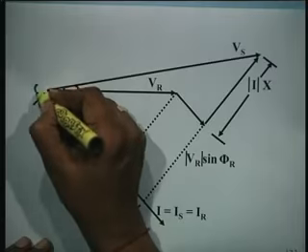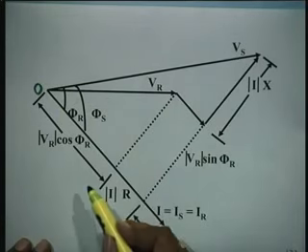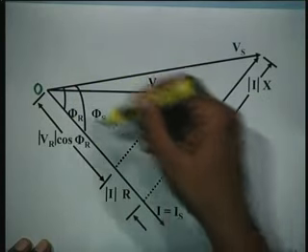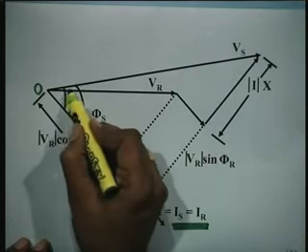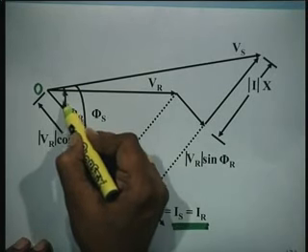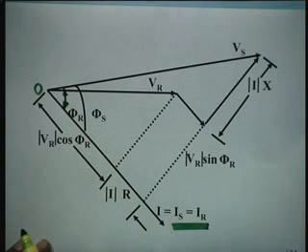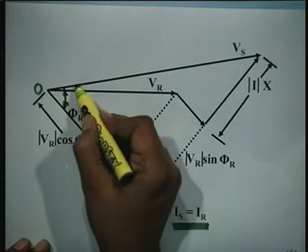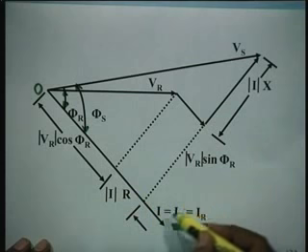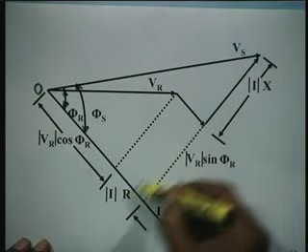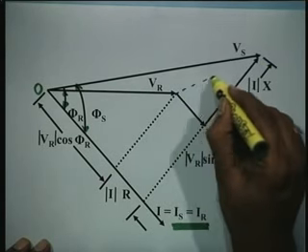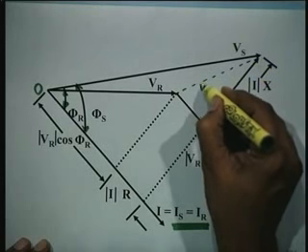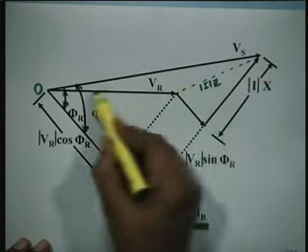This is origin, this is Vr, this is the current, which is same as Is equal to Ir. This is receiving end power factor, this is sending end power factor. You add this Vr, the resistor drop, add reactance drop, and this is nothing but Iz, and this is Vs.